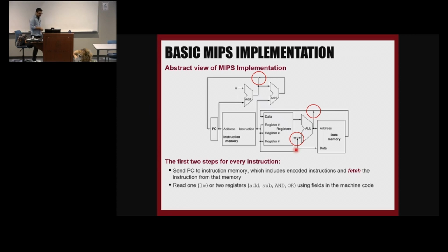A multiplexer is a very simple block. If you don't remember it from a digital circuit design or digital logic design course, we show it like this or this, it doesn't matter. Usually we have 2^N inputs and one output, and then we need N select lines to select each of these inputs.